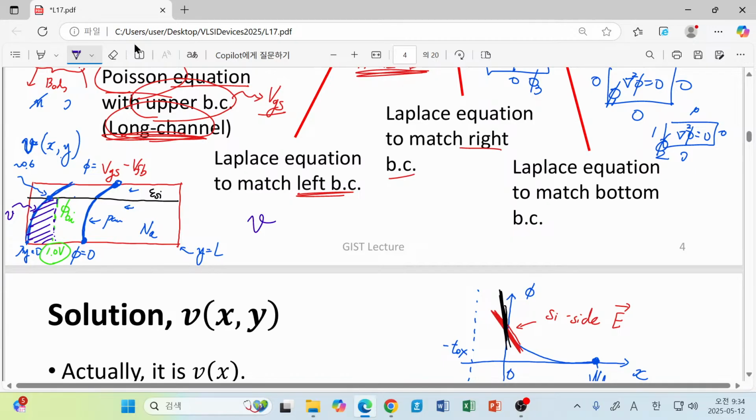By considering only V, the value determined by our top gate potential, the boundary condition for this top surface is completely satisfied. Oh, we are happy. And by using the homogeneity of V over x and y, now we have a mismatch in our solution. Although we have a well-defined boundary condition, it is not corresponding to our solution V.